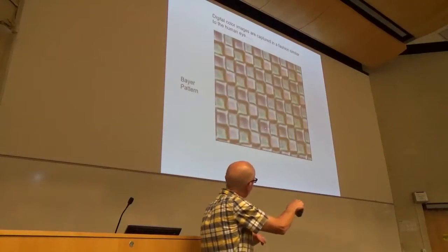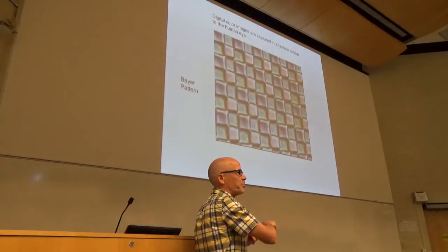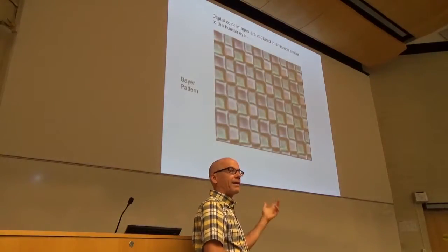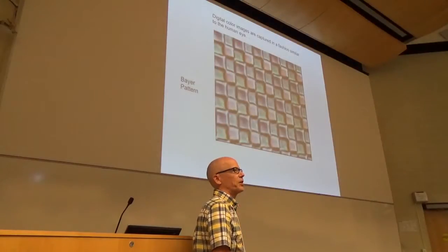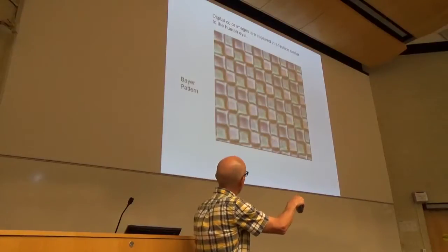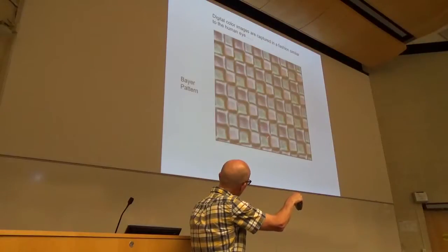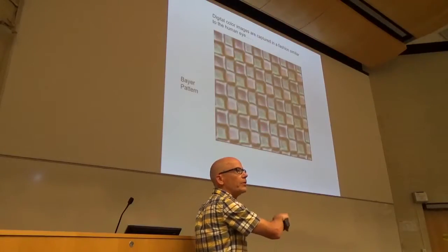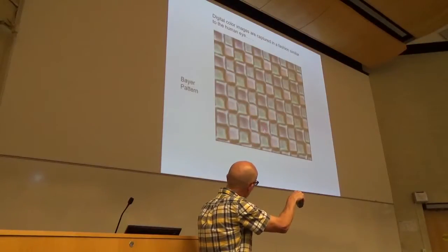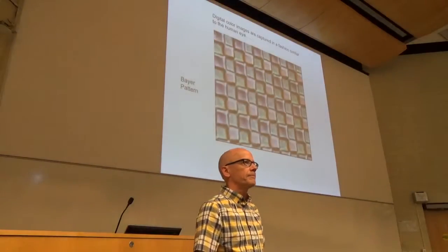So when you think about that pixel right there on your image, it's only detecting blue light, right? So how do you get a color version there? Well, you have to interpolate the pixels that are around that. I've got my blue measurement, but I'm going to interpolate these 4 green pixels to estimate what the green would be there, and I'm going to interpolate these 4 red ones to estimate what the red would be there. Now I have a blue, a red, and a green value, and I can get a color from it, right?